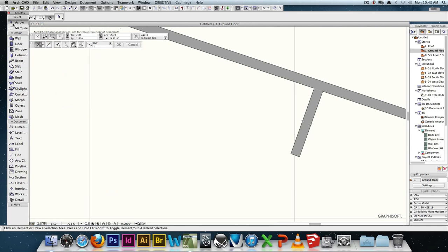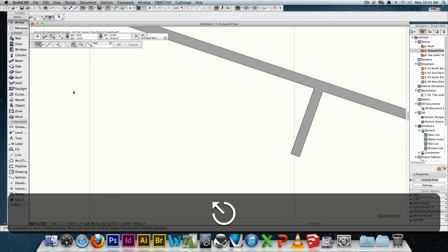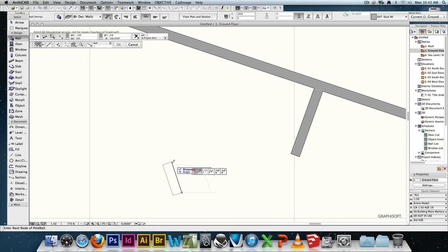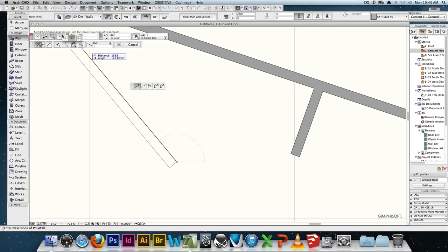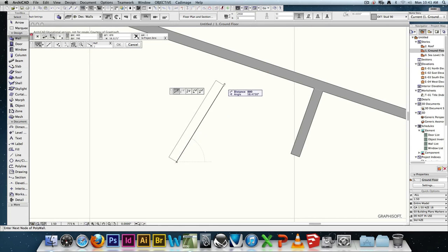Yeah, so you can turn it off in here. Let's say you wanted to start on the grid, and you'll see this a lot in ArchiCAD. So that's still snapping to my grid. See my little cursor's running around? But I can actually switch that off while I'm still drawing. So that end snapped to the grid, this end isn't. And so then I can go, excellent. That end will be a nice measurement, well, to my grid at least. And the other side won't.